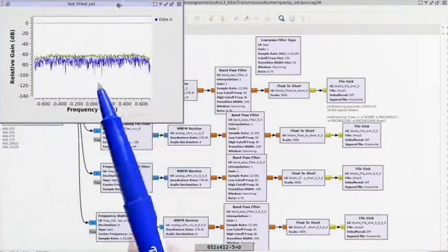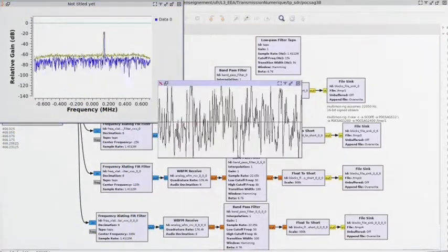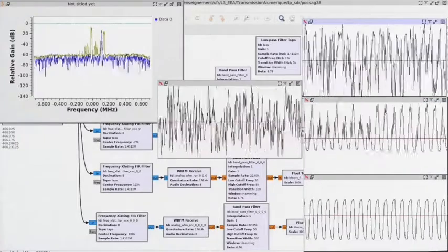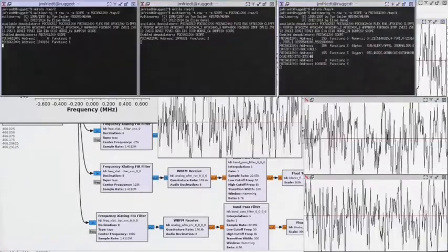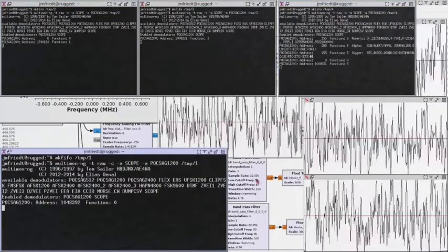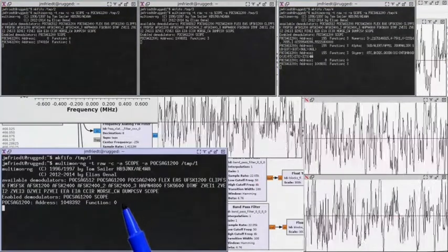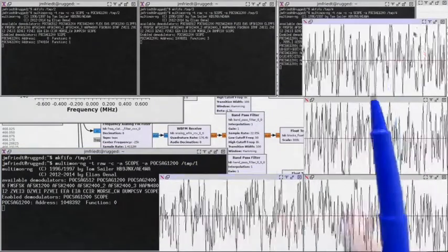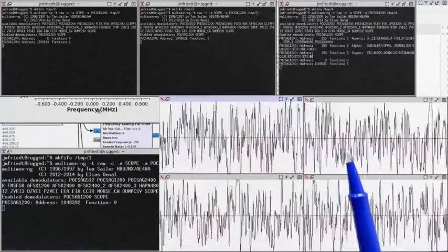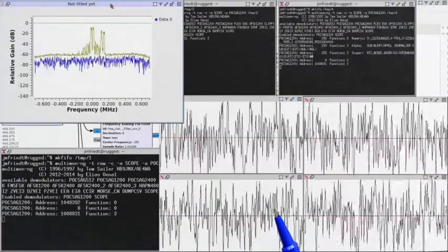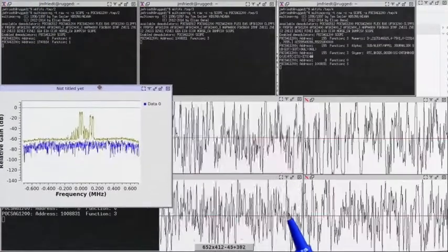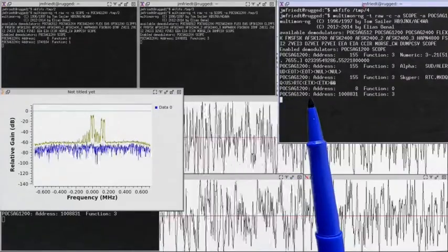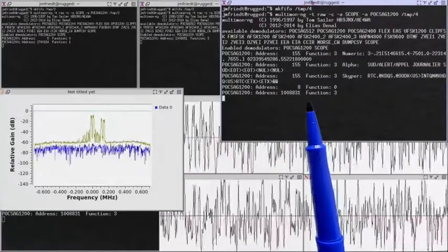We've seen already one communication, middle button, and we keep the maximum value. And here is the first communication. We've seen it every time: the preamble is these periodic oscillations followed by the message being transmitted. This channel here is mostly maintenance, but here we already start seeing some messages coming in. When there is noise, of course, the scope output is a random signal. Here we've seen the preamble followed by the message, which is immediately decoded by one of the terminals here. We will magnify this one because there are some more interesting messages on this channel.